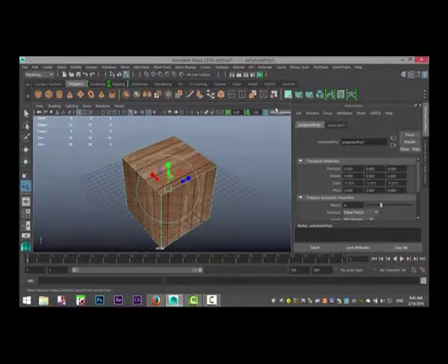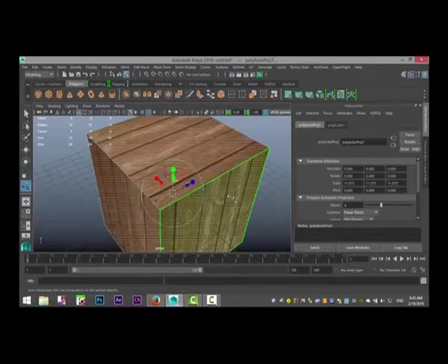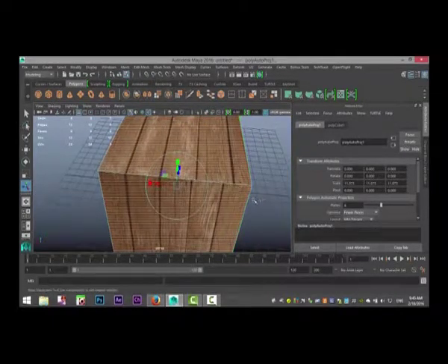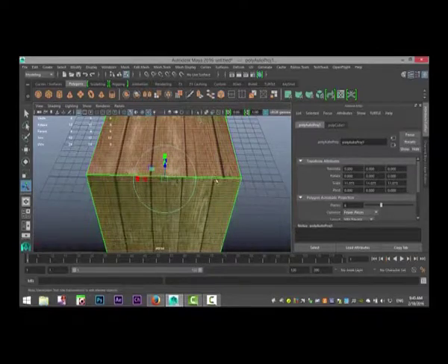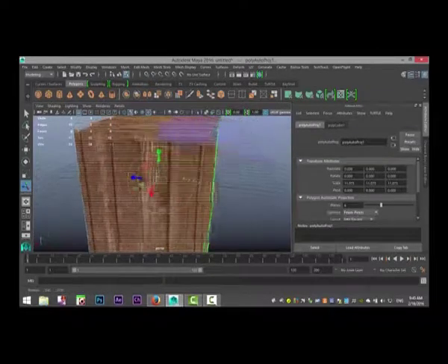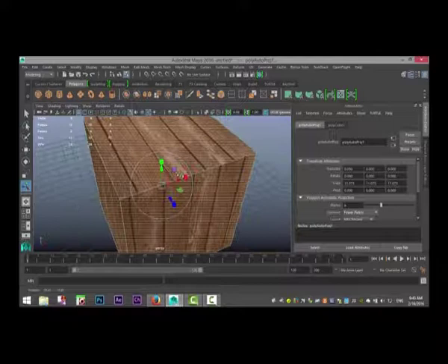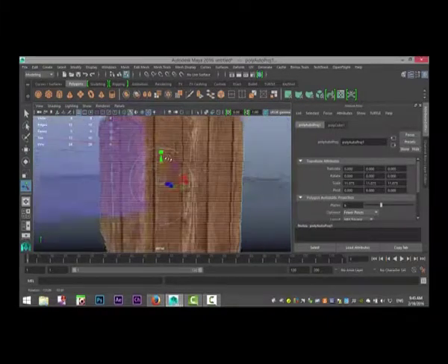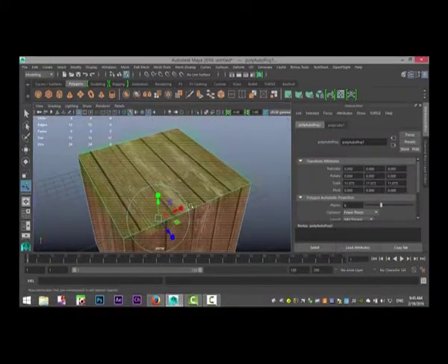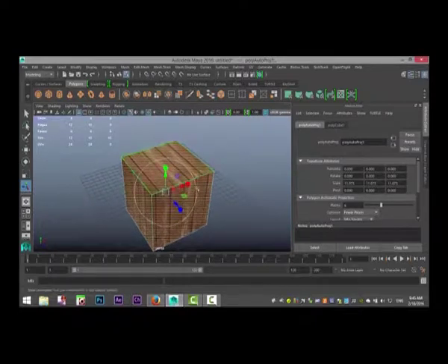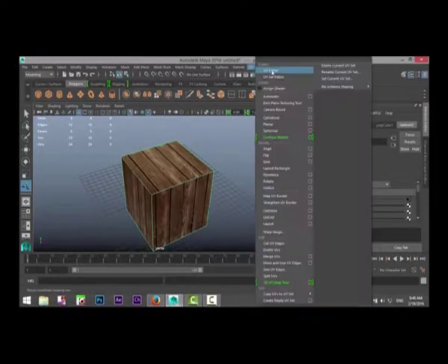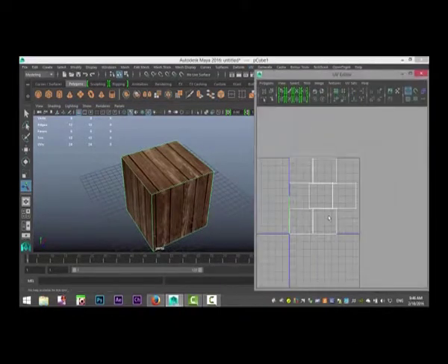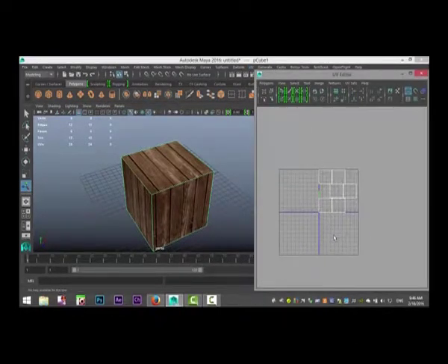If you turn off the normalize option, the applied texture will not resize and it retains its true size. The normalize collectively option maps the texture over each face of the primitive and normalizes it so that it covers the entire object. You can also normalize the texture for each face separately. We will study the UVs in detail in the coming sessions.